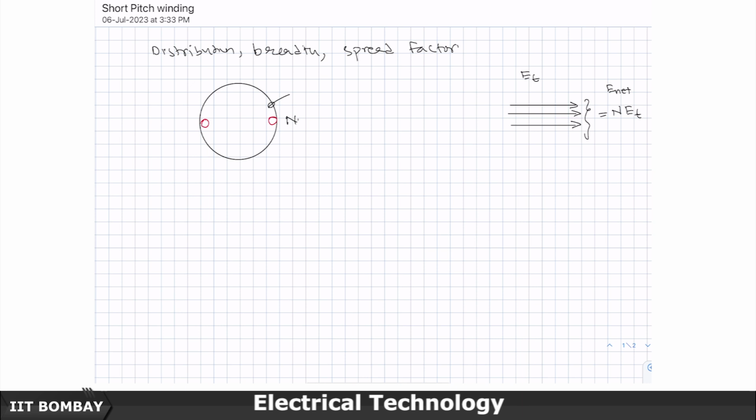The space which you see here is not utilized. That is one thing. The other thing is, when I do the derivation of the rotating MMF very soon, you actually want B to be distributed in space in a sinusoidal way. That is something we are very keen about.